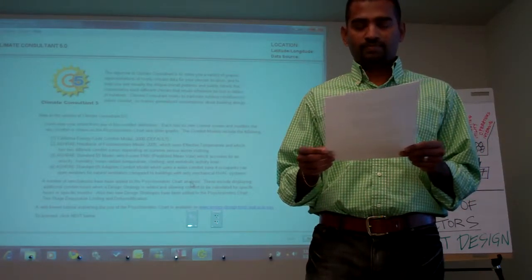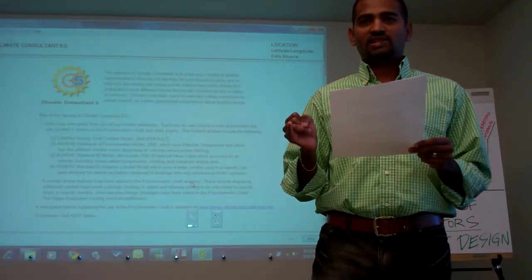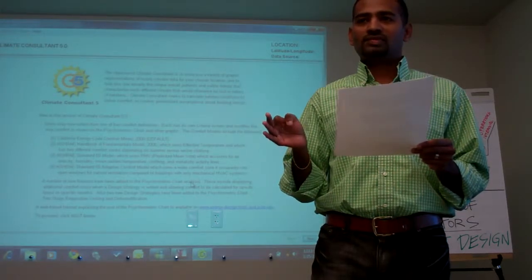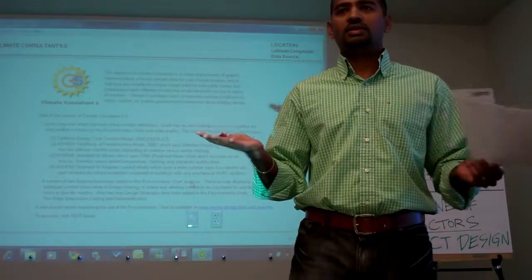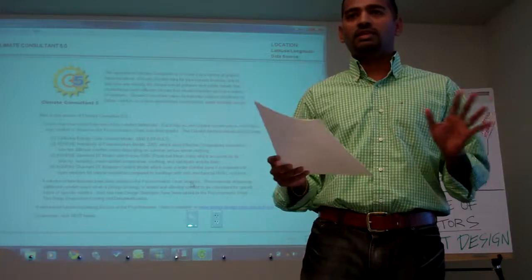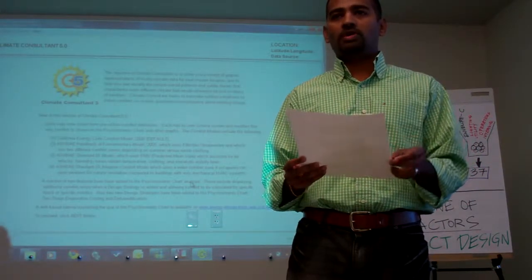List the 5 most important ingredients that go into an analysis tool to determine your building's design EUI. Envelope. Operations. Comfort. Internal load. Utility rates and outlet load. Last one, systems, mechanical. So we need these. There are so many other things that go into the design analysis model, but these are the 5 most important points.